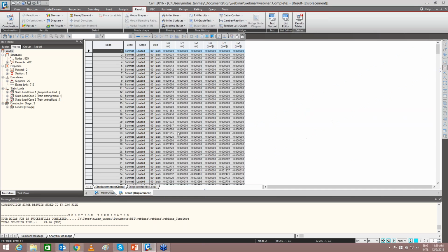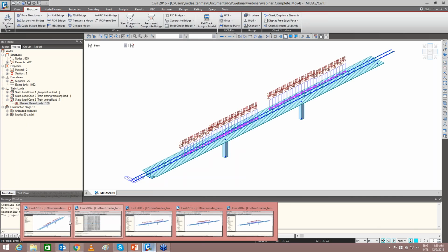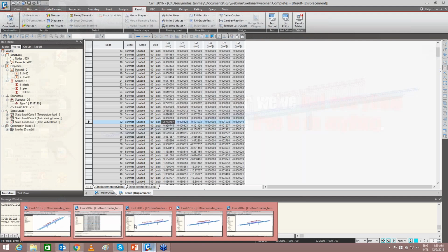So for this, we can just go there in the table and we can see the displacement, the Tx value, see it in millimeter. So 32, 33 and 34. So using these values, we can calculate the relative deformation that is occurring in this case, and that can again be checked with the limits provided by the UIC 774-3R code. And for all the models that have been generated, we can do the analysis and find out which is the worst case for the various positions of the load.